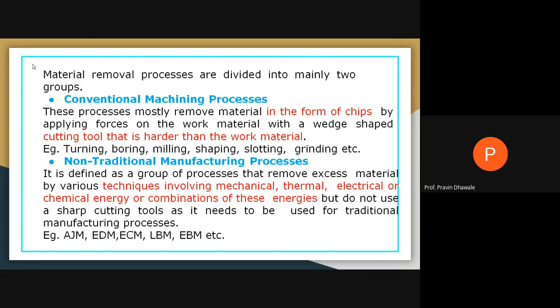But such processes do not use a sharp cutting tool that is needed in traditional machining processes. Means in non-traditional or non-conventional machining processes, the cutting tool is not required. They utilize different kinds of energies in order to remove the material from the workpiece.